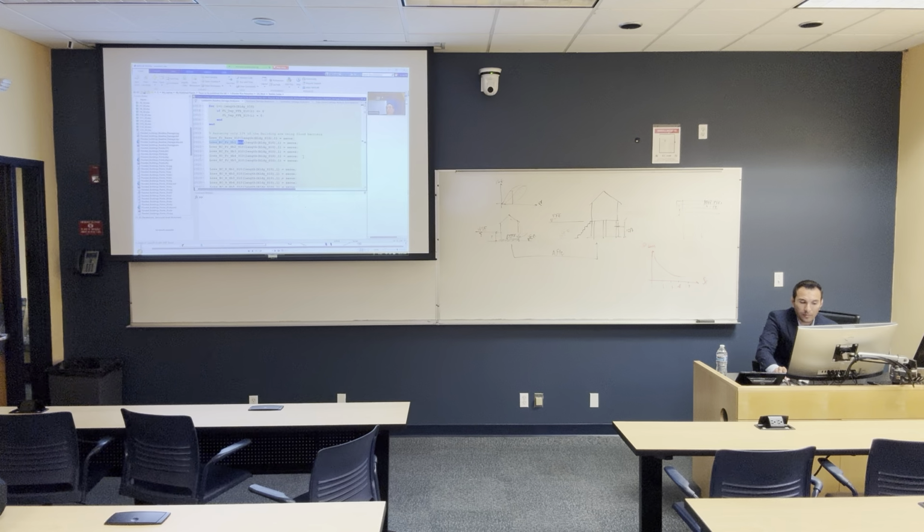And I'm preparing the matrix, I'm putting zeros here, and here I'm calculating flood loss reduction, and here I'm calculating reduction total for HB1 and for 10% of the building. And it is the same code from last time. I'm saying for buildings that are archetypes 1 and 3, calculate the base flood loss. And for the base flood loss, I use the F3D loss at D5 because I know that 10 days is considered as the base flood loss without any duration included.